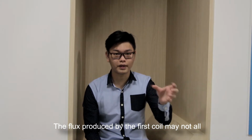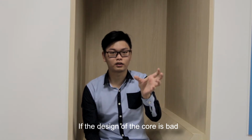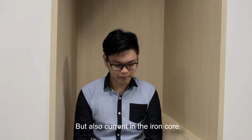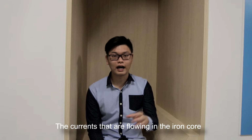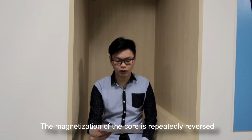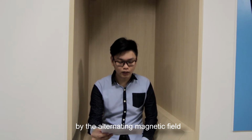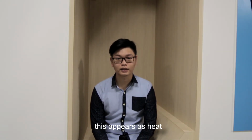The flux produced by the first coil may not all transfer to the second coil if the design of the coil is bad. The next is eddy current. The changing magnetic field not only induces current in the second coil, but also current in the iron core. The currents that flow in the iron core are eddy currents. Eddy currents cause a lot of heat loss. Another issue is hysteresis. The core is repeatedly magnetized by the alternating magnetic field. This process expends energy, and this appears as heat.